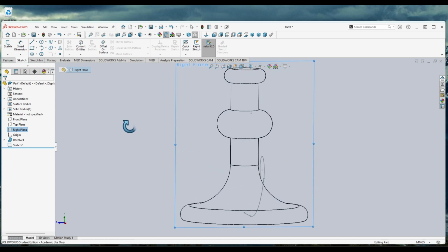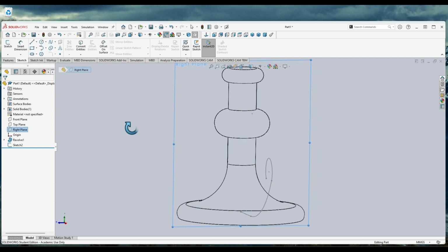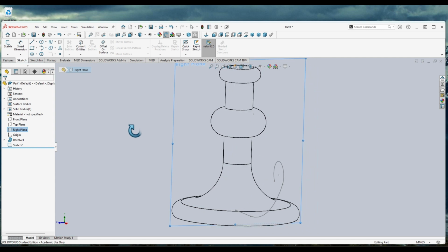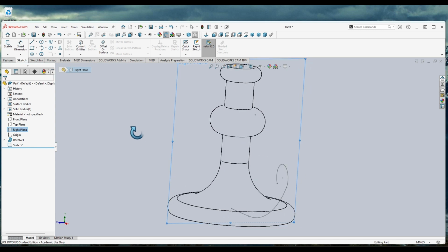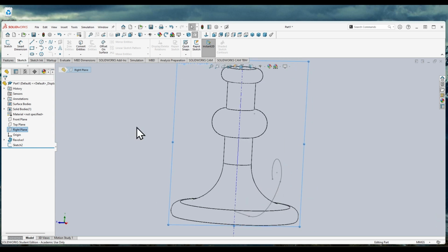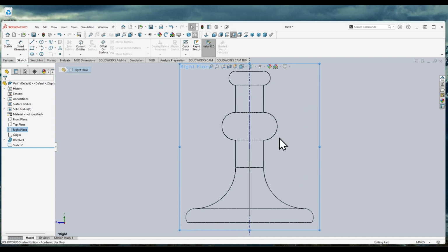I'm going to turn it a little bit sideways while holding down my middle mouse button on the gray sketch area. I'm able to manipulate the 3D view of my object here. We can see now that the candlestick rotated and the tail is kind of towards me. So I'm going to hit the normal button again to get back into that view. It's kind of hard to tell because it's 2D on our screens, but that tail is coming towards me.